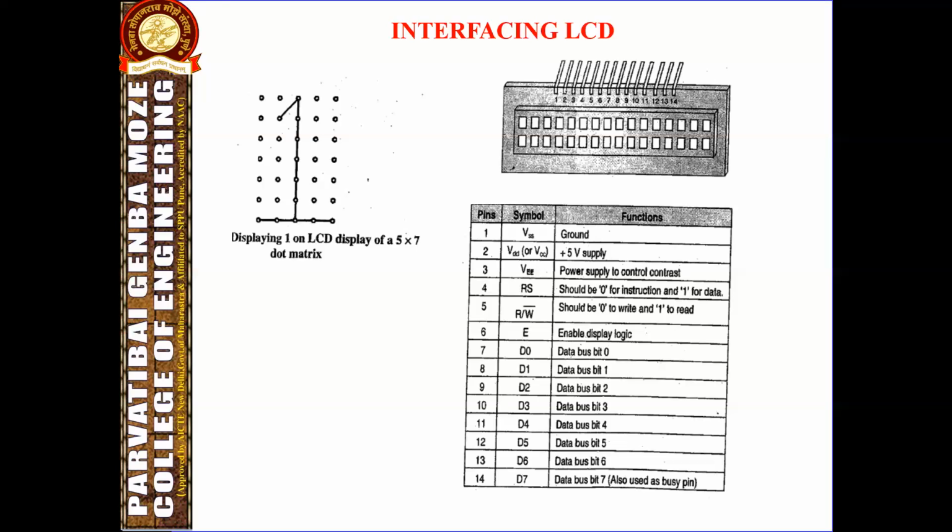The ASCII code to be displayed is 8 bits, and it is sent to the LCD in either nibbles or bytes. The two primary modes of operation to send the parallel data are 4-bit and 8-bit. If the 4-bit mode is used, two nibbles of the data are sent to do an 8-bit transfer. The E pin is used to initiate the data transfer. At least 6 IO pins must be available for 4-bit mode. In 8-bit mode, at least 10 IO pins must be used. This mode is used when the application needs speed.